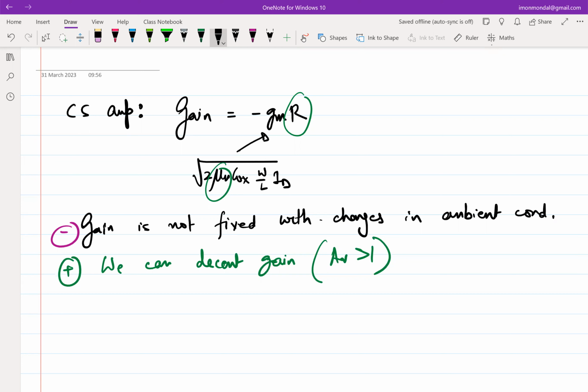If we take a voltage divider, you take R, you take the midpoint, you get R by R plus R. Both the R's vary in the same direction regardless of the change of ambient, in the same proportion rather. If it varies by the same proportion, then the ratios will be independent of temperature. Similarly, if you take ratios of GMs, they will be independent of temperature because the temperature variation of those two GMs will be mostly identical.